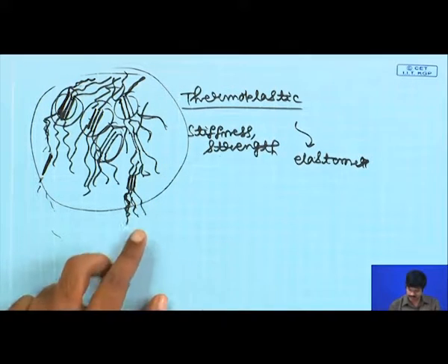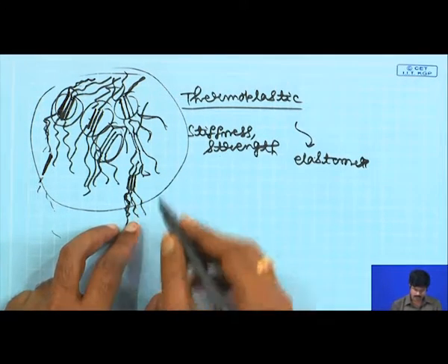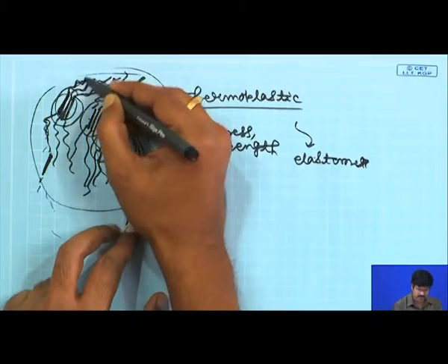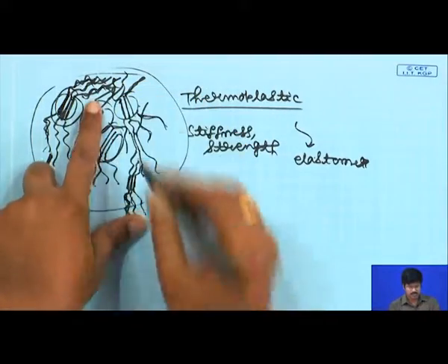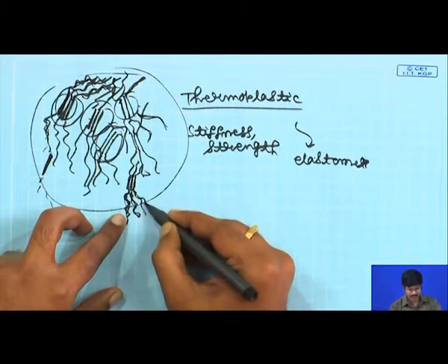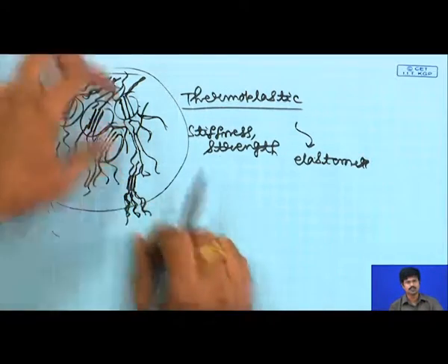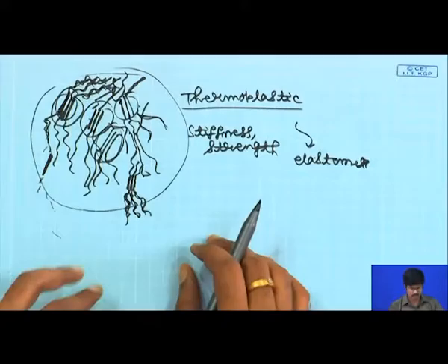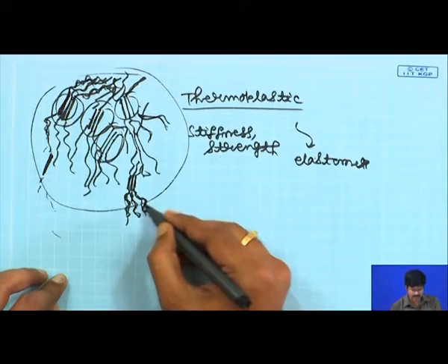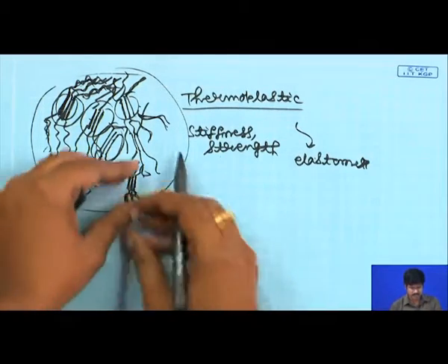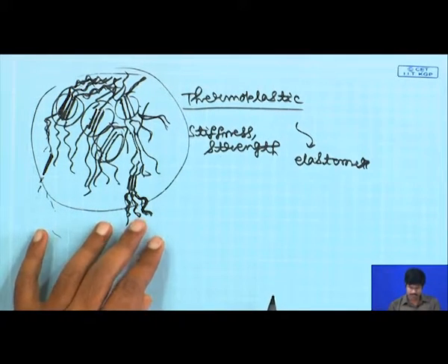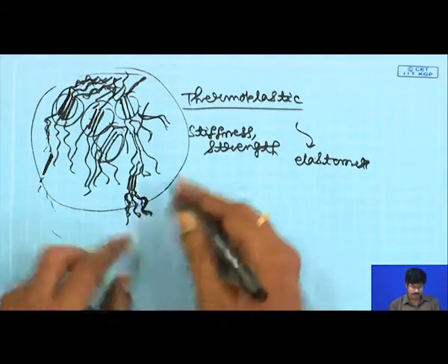Now, these soft segments are coiled sometimes like this, or they are wavy like this. So, what you can do when you are extending this material is continue to extend until these soft domains are extended to their full length. At that point they will break, which is the breaking point at which all these flexible chains become straight. So, you can say that these flexible chains contain hidden length, so they can be extended. From there your stretchability will come, because your material is stretchable.